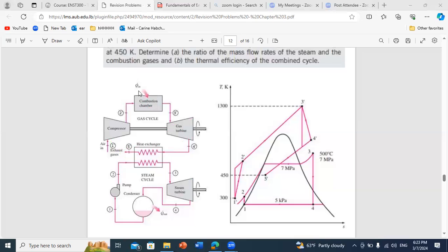In general, why are Brayton cycles characterized by low efficiency? Because it's an open system and you reject gases at very hot temperature. But the advantage of this cycle is that it can produce a high amount of power. So it is used, for example, in aerodynamic applications to drive airplanes. But even inside, let's say, the airplane, you might have some heating needs, maybe water, or you need to drive another cycle. So you can benefit from these exhaust gases, and it can be used to produce electricity.